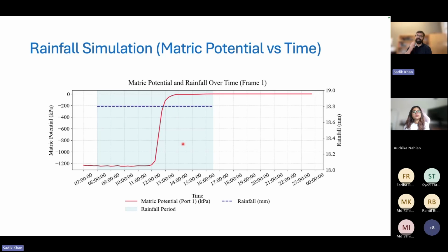And I personally feel that instead of relying on the shear strength, utilizing the evapotranspiration is a better approach to slope management than just relying on the shear strength of the slope. Because when we utilize the evapotranspiration characteristics of the plant, it not only draws the moisture from the soil, it also reduces the load because the unit weight goes down when it pulls off the moisture from the slope.